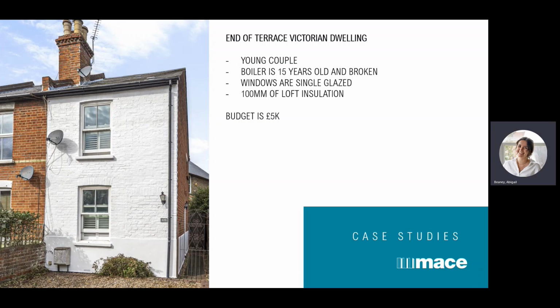So from looking just quickly at this project, we can make a few assumptions. We can see that the brickwork here is a short and long formation. So it's very likely that this is a solid wall construction, which is typical for that era as well. So we could be quite confident in assuming that. So we can think to ourselves, oh okay, one of the best measures here, we could propose external wall insulation. We could wrap that property, that would help with making those cold walls warmer.